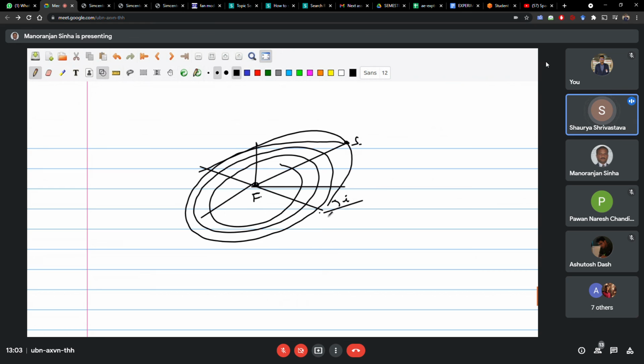And argument of perigee cannot change in plane. Argument of perigee can rotate while staying in the same plane. See here, if v is the velocity here, and if you produce any change delta v here, the argument of perigee remains the same. But if anywhere else it receives an extra impulse, the argument of perigee will change.